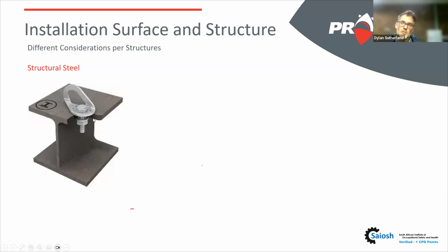So a general way to contemplate whether or not this would work, imagine a 1.5 ton bakkie being lifted by a crane and connected to that structure and just let go, not dropped, just let it hang. If that structure can hold that 1.5 ton bakkie, you're probably good.